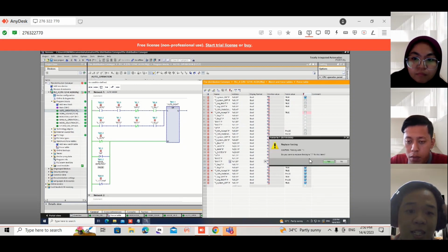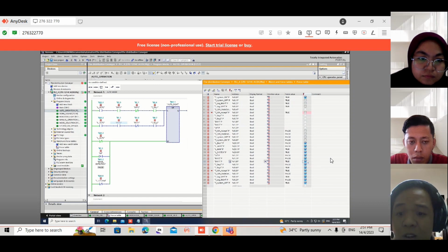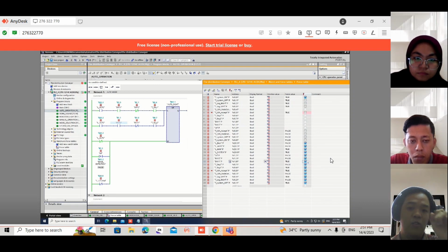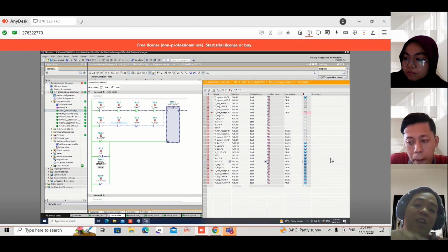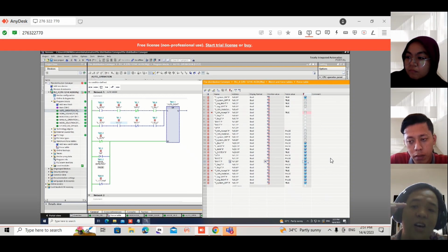We will use the proximity sensor in bay 1 and bay 2 to start the conveyor belt, and we will still use the momentary contact for the occupied bay to control the movement. The only change is that the conveyor motor will stop as soon as the part passes through the light barrier, even if the auto mode is still on.